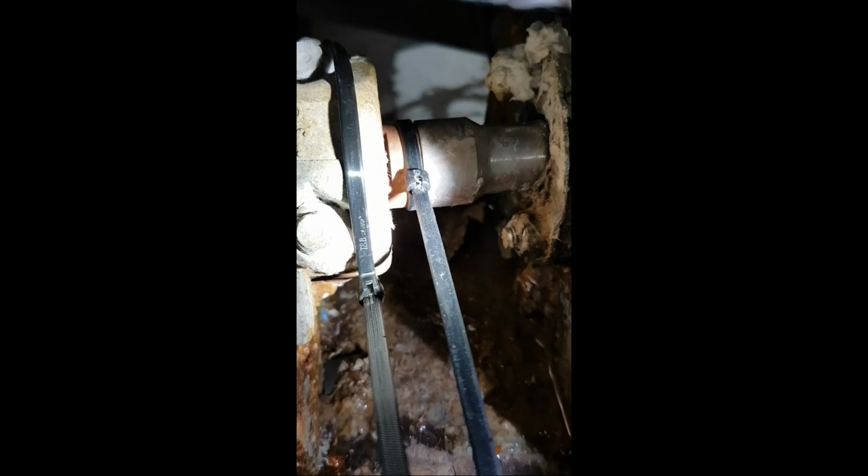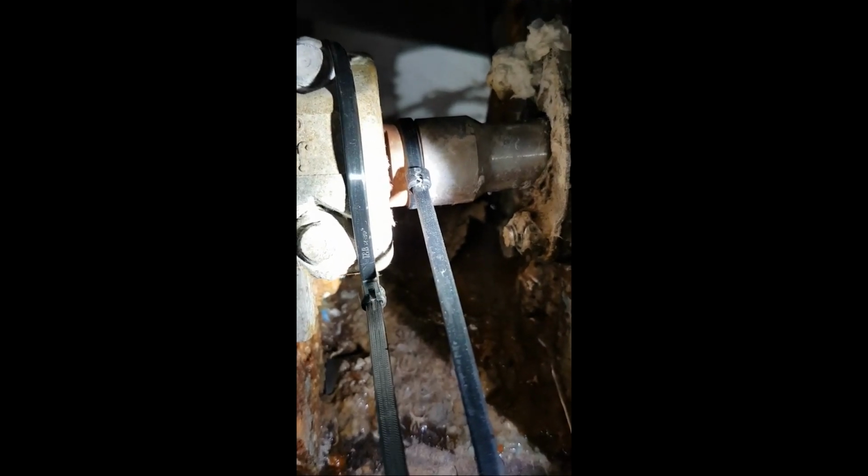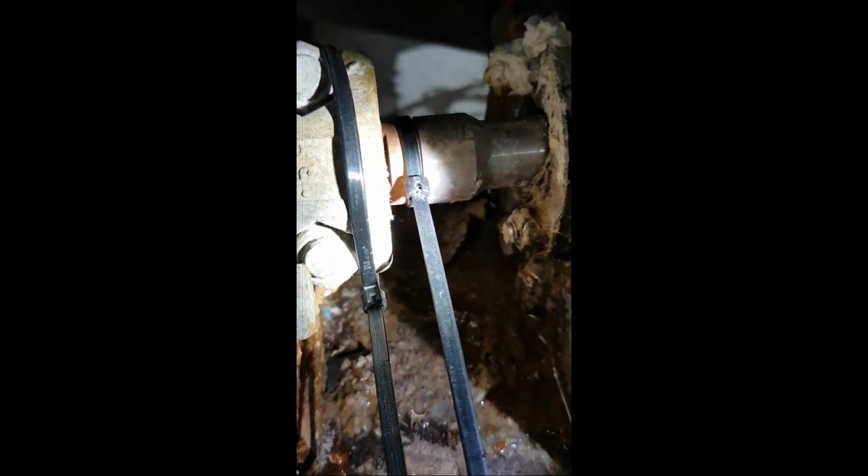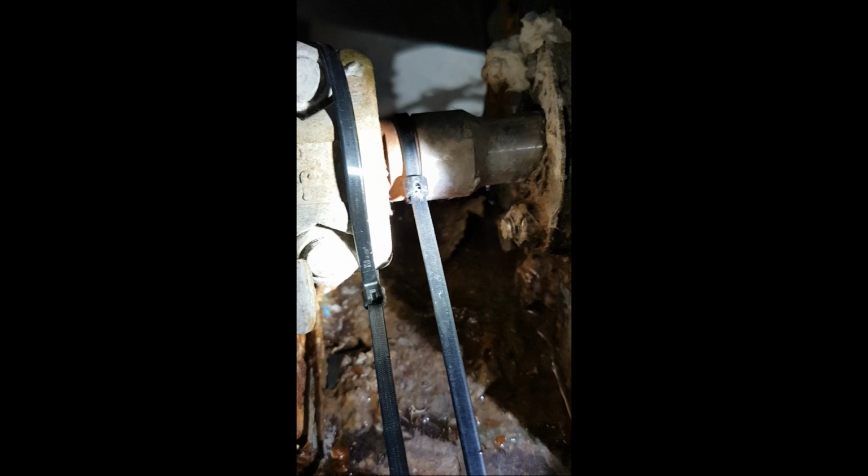Now the valve's moving. Now it's going to go the other way before it actually engages. So it engages. You see it had to move up. I estimate there's probably 5 or 6 degrees, at least, before it mechanically engaged on the other side. So you can see here a very, very typical case of hysteresis right there.